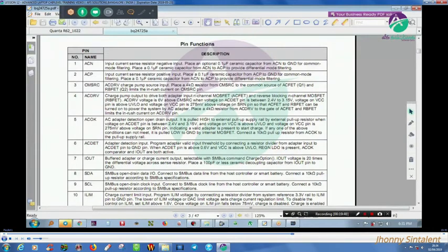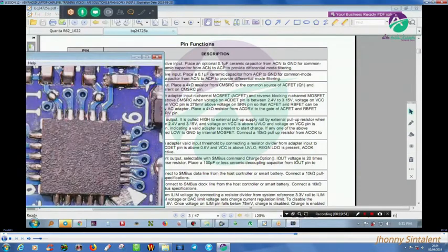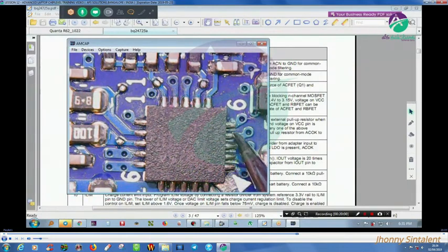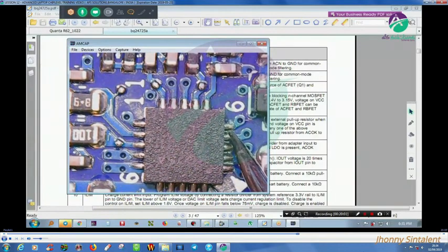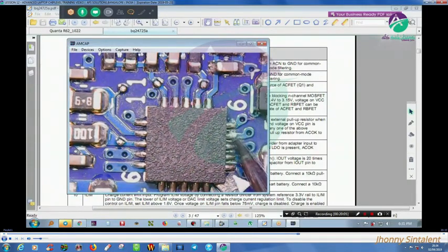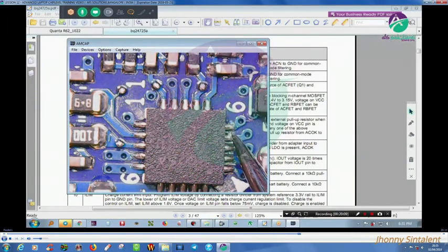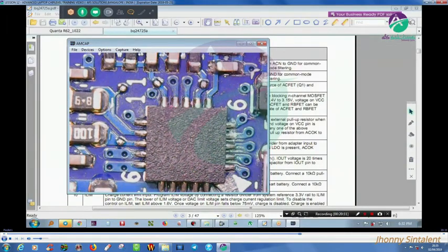So pin number 4, let me check here only, it will be better. So pin number 1, AC in, negative positive, AC drive is pin number 4. I don't need to go there, I can check here itself. So if you go for pin number 4, this is pin number 4. Pin number 4 is 0 volts. You can see this pin number 4 is showing me 0 volts. I think this is the problem here.